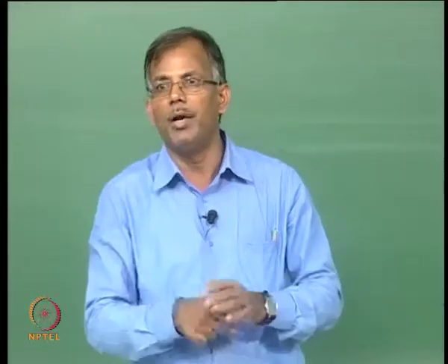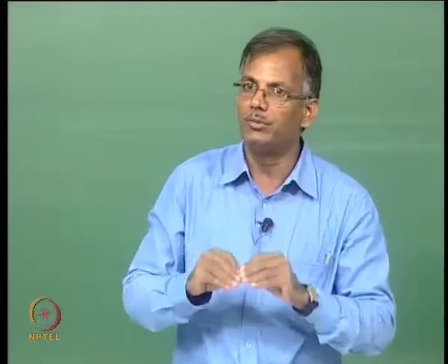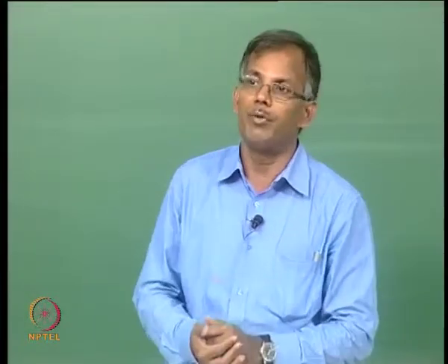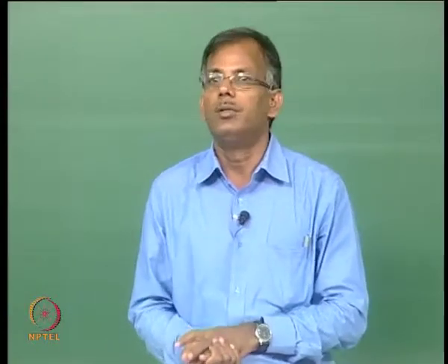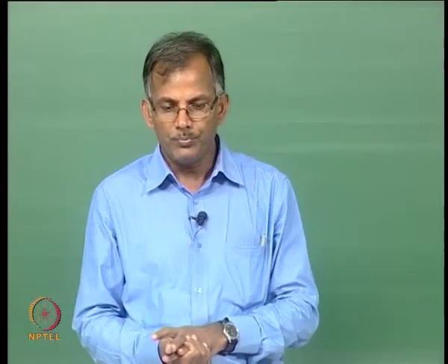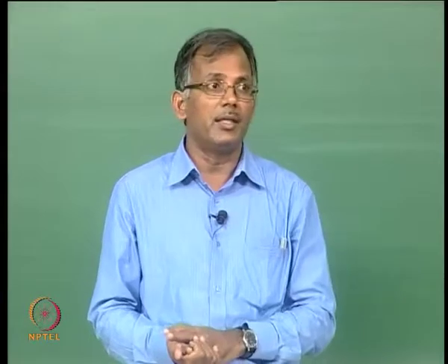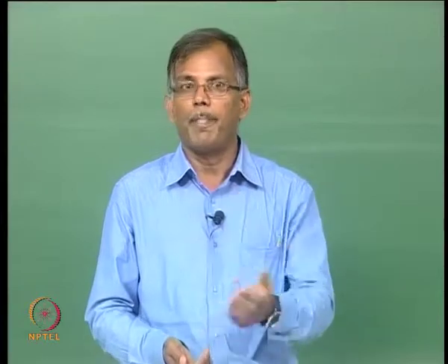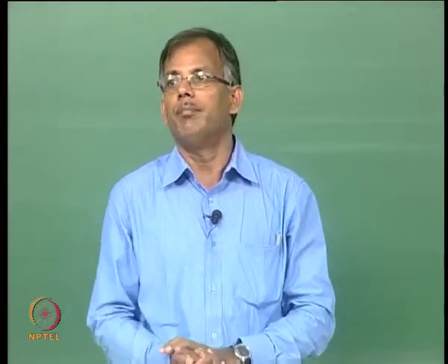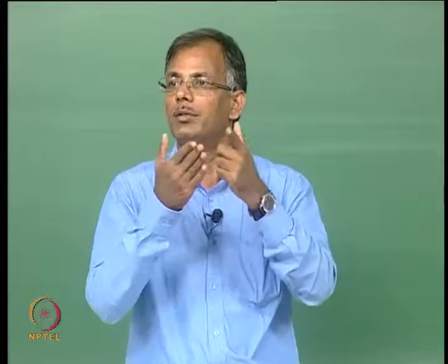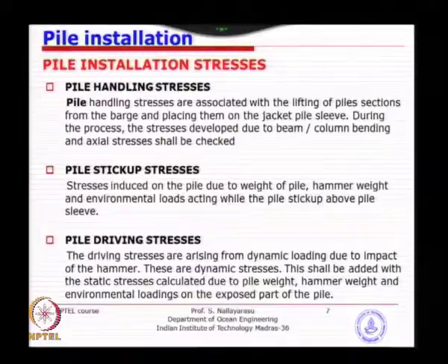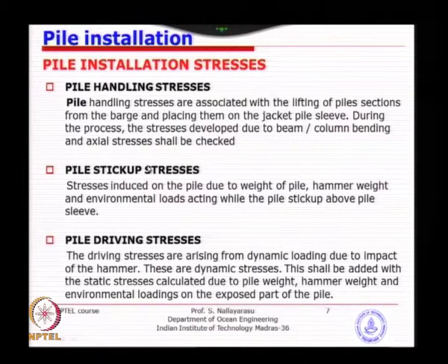So, at a particular point you will see a compressive stress while the stress wave is travelling downwards, while when the stress wave is travelling backwards during reflection, you will see the pile subjected to tensile stresses. And that is why when you are actually taking a small nail driving against a hard wall, what will happen? The nail will start coming backwards, because it is unable to absorb the energy into the hard material. So, these driving stresses are as important as the stick up stresses and must be handled carefully.